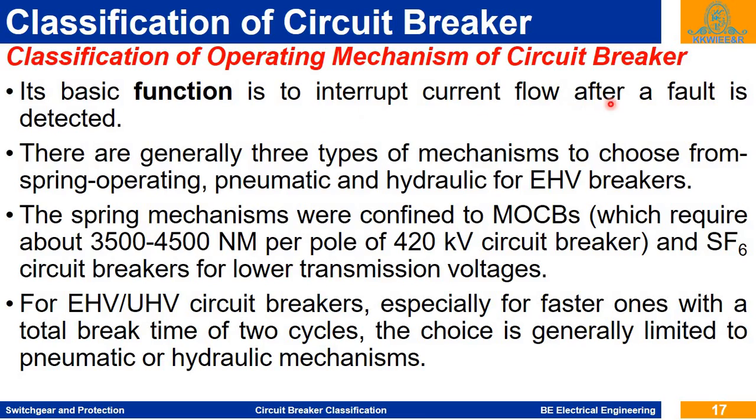During this fault or abnormal current, which is in thousands of ampere, heat is generated when the contacts are separated, and to avoid damage to these contacts, a fast opening or fast movement of the moving contact is required, and at the same time the interrupting medium is injected on the arc.